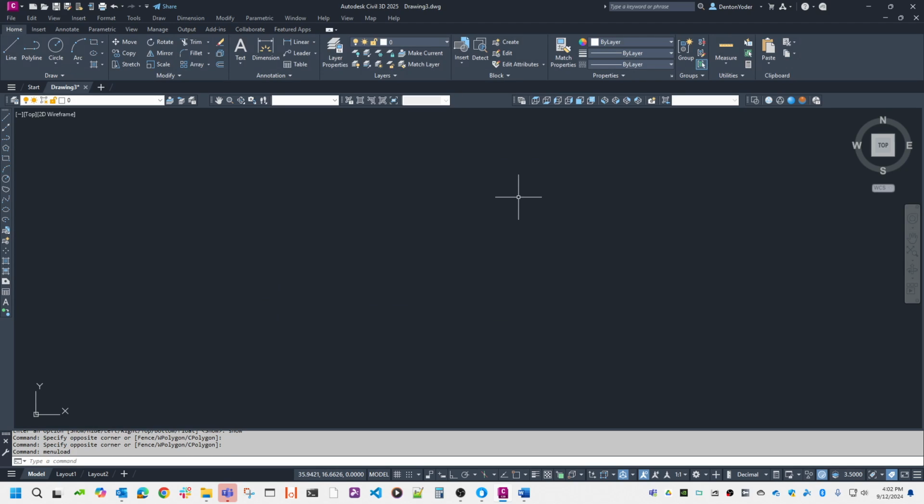Okay, so what that's done is we've started AutoCAD. We've set the work group to our own name. We've loaded the menus and the toolbars we want. We docked the command line. We turned the menu bar on. We turned off the dynamic input. I think I'm happy.